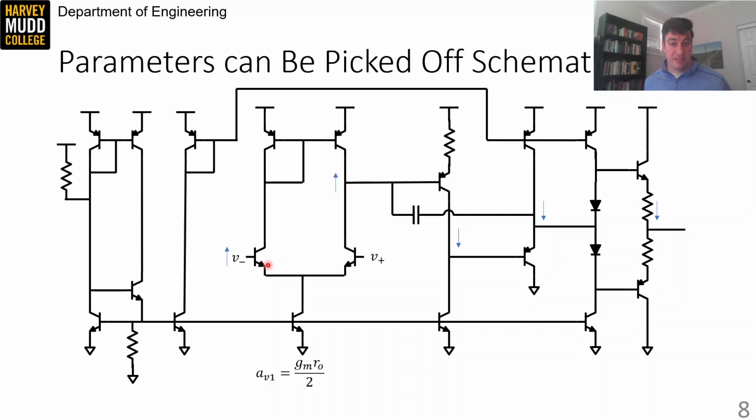We find gain in the same way we always have. The differential stage is a single-ended differential actively loaded diff amp, so its gain is gm ro over 2. Interstage loading is given by a divider between the diff stage output resistance of ro over 2 and the gain stage's input resistance of beta re. And finally, the gain stage resistance is ro over re.